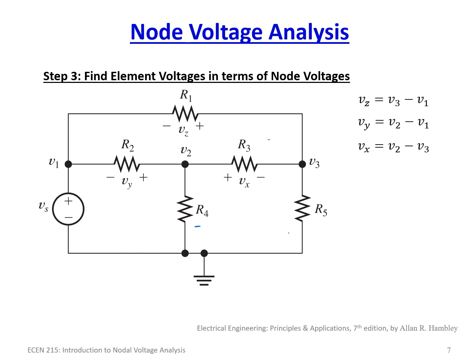Now, what else do we know about this problem? What is V1? Do we know what V1 is? If this was an actual circuit analysis, we would be given what Vs is. This could be, for purposes of argument, 12 volts DC. So you're given Vs. This is a known. So what is Vs? Vs is simply equal to V1, because that is the node and it's an ideal power supply, and that ideal power supply is going to maintain the voltage with reference to its reference node here to V1. So no matter what's assigned here, if this is 20 volts, V1 is always 20 volts. It doesn't matter what else is connected to this.